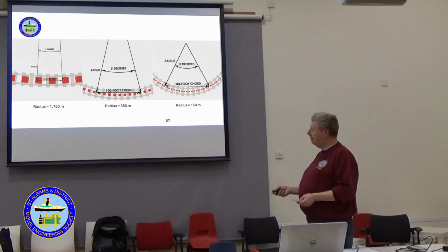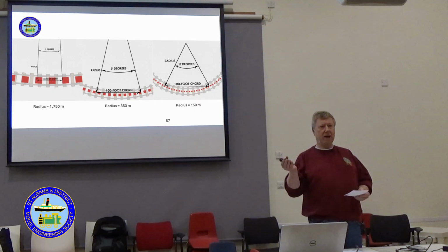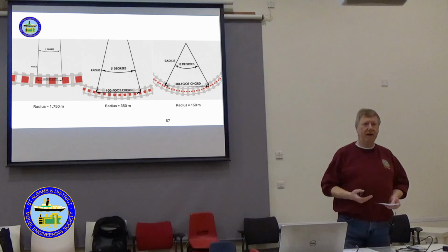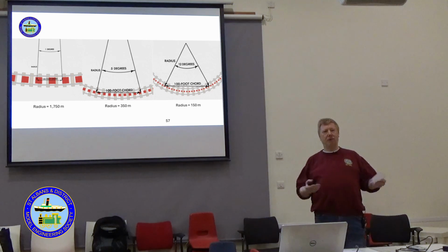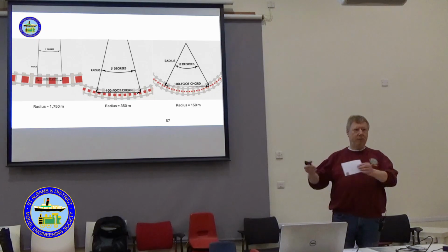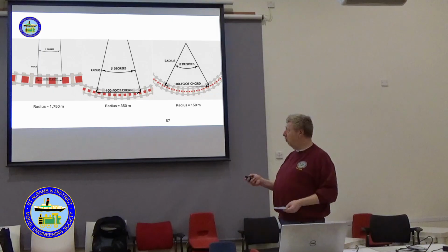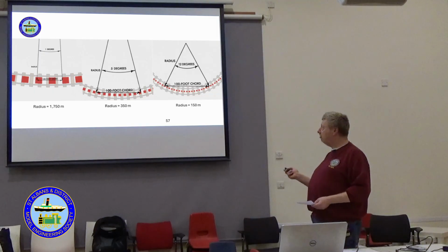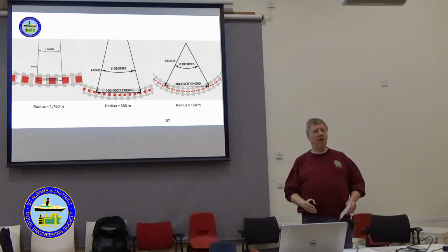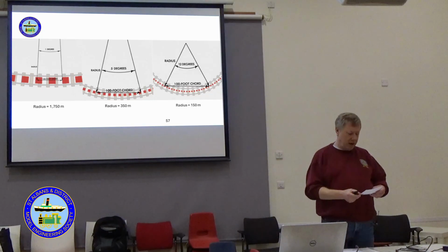Now the thing about curves is the curves add drag. You know we said earlier about the squiggling as it goes round the corner? Well, that's the flange rubbing on the inside of the rail. Rubbing, not good in engineering, that is wasting energy. Plus you'll find that all of these have speed restrictions. So you're constantly accelerating, decelerating, accelerating, decelerating for each of the curves.